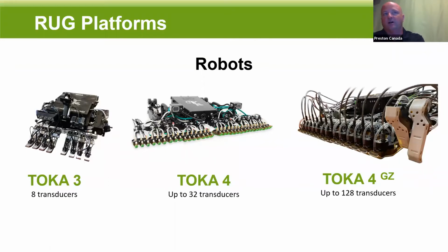support. The robots that we have, well, they're on this screen right here, they all have a limitation of a 1/2 inch 90-degree transition. So if the transition is about a 1/2 inch to 5/8 and it's at 90 degrees, that's our upper limit. So most flanges we can't get over, most pipe supports we cannot get over unless there's a clearing on the top of it. If we can drive around the bottom of the pipe support, then we should be able to transition to the next section. But sometimes it is more time effective just to move it and place it.